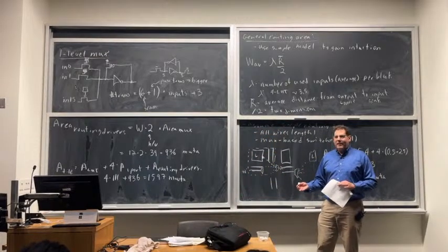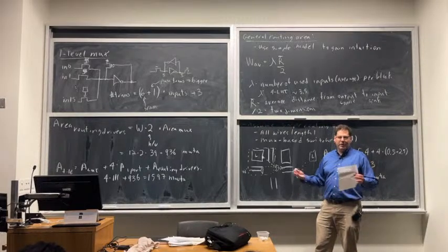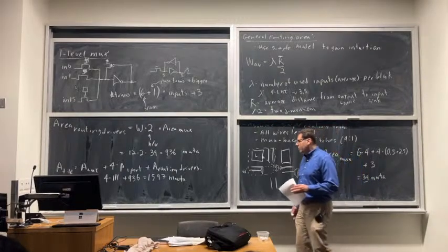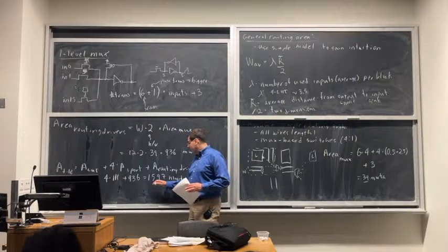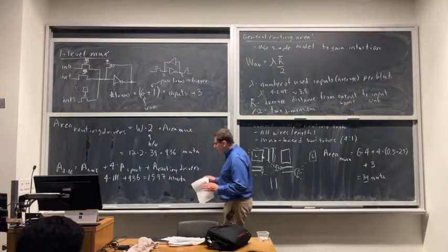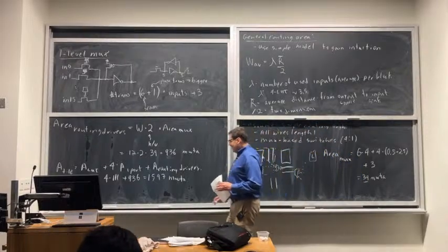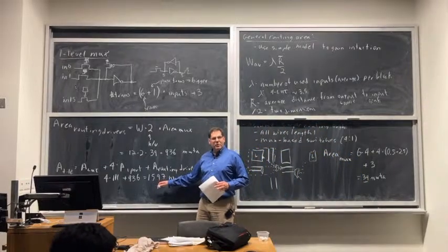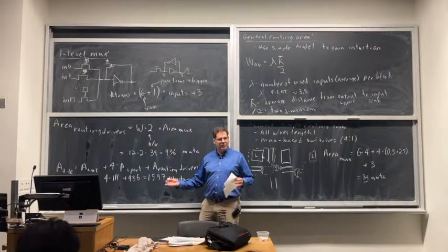Now a LUT can implement several gates worth of logic usually. Just putting a single NAND 2 gate in it would be underutilizing it. So it can usually do several, maybe as many as 5 or 6, but that's probably about the most you would get on average. So this is quite a bit of area compared to a gate. It's showing us part of why programmable logic is less efficient.